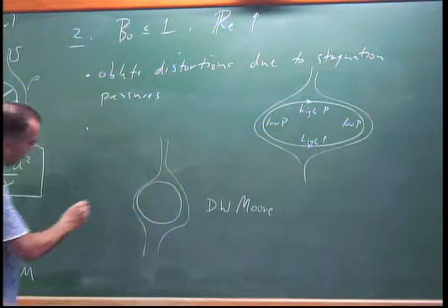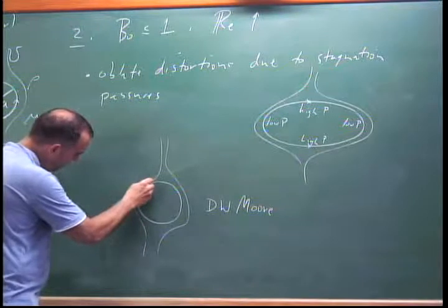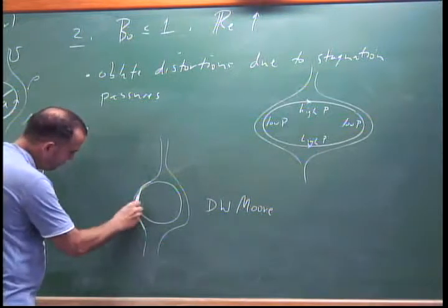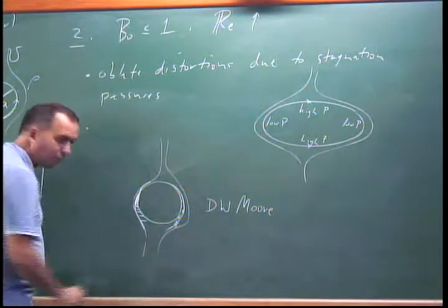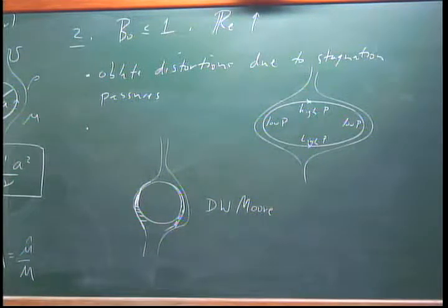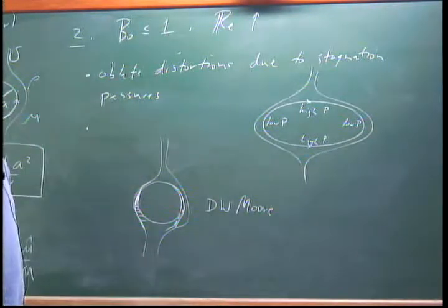But in fact, if you impose the no-slip condition on the surface, then you actually generate vorticity, so you get this viscous boundary layer where your potential flow solution doesn't work. And so you actually have to solve a boundary layer flow and then match it onto the external flow, and you find the dissipation in this boundary layer, and that's what gives you the drag on the object.